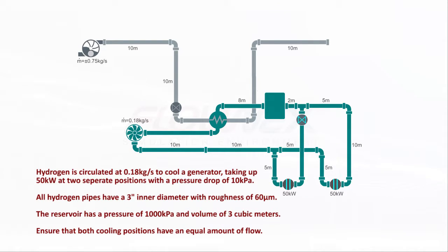Now this is where the challenge lies. Since the pipelines have different lengths, therefore different flow resistances, we have to add resistance to the shorter pipeline using an orifice or valve. So getting all the flows and pressure drops to the exact specified values will take some planning, and the correct use of boundary values, fixed mass flows and other tools you've encountered so far will be imperative.